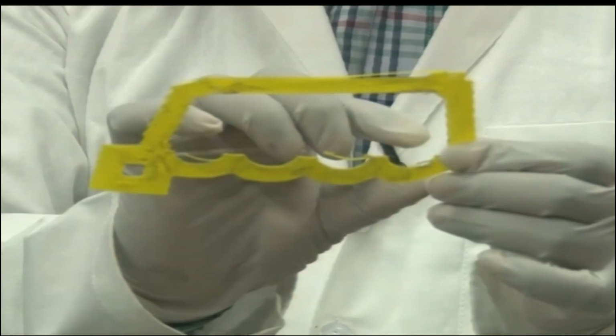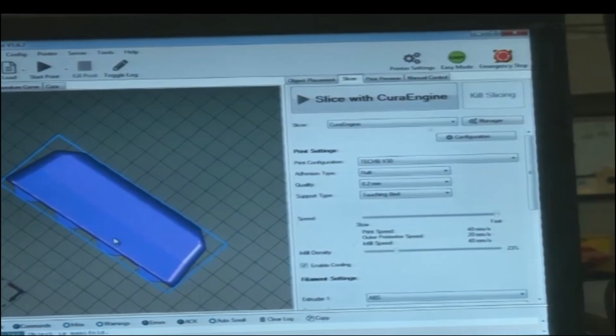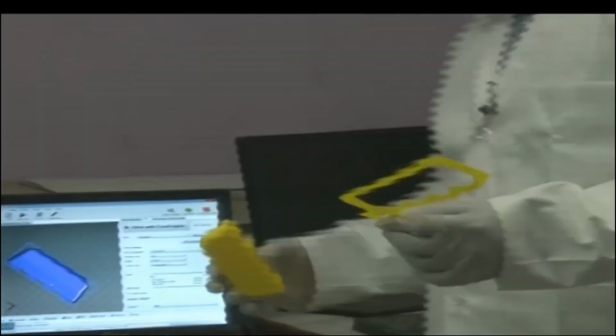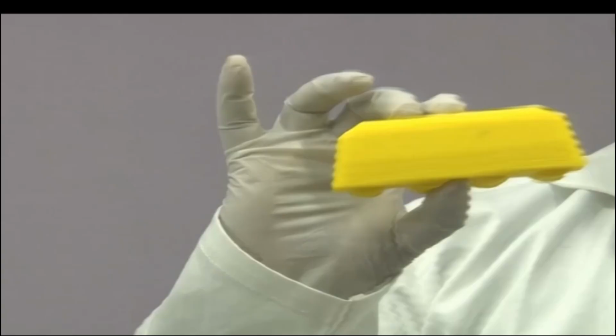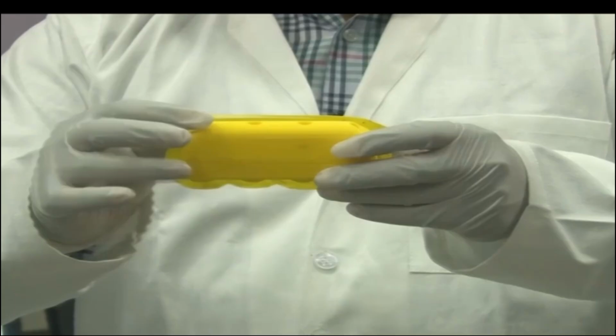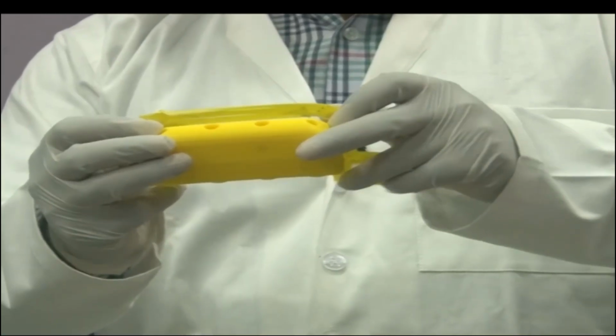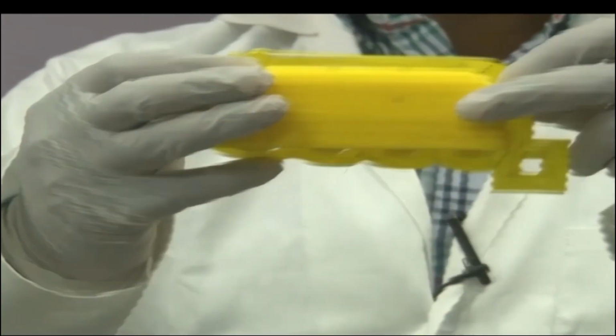So we are talking about the selection of brim here in the software. When the nozzle head starts printing, it is the actual model that we want to print, but it will deposit a little extra material to produce this first layer. This is actually the brim. Okay, this is the model that we have. This is the model that is produced. So it will deposit a little more material. So this material was produced in this way.